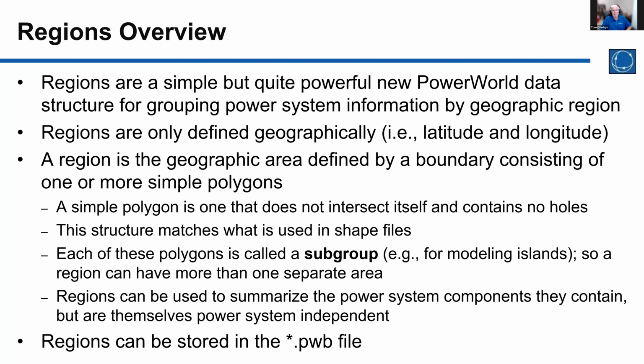And then the idea of regions is that you can use them to easily summarize power system information. And then I'm going to show you that you can also use them to visualize power system information. And I should say regions can be stored in a PWB file, but you can also load them from an aux file. We'll get into the details in just a second.